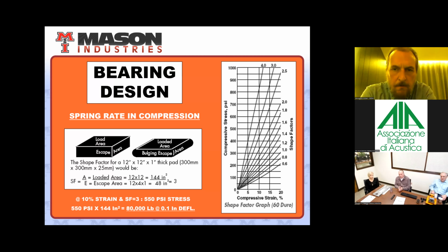Some of the things that people do in error is overstress a bearing in a building isolation project, and that significantly reduces the longevity of the bearing. So low stress, low strain is a concept that we've evolved with, and it has worked 100% of the time.